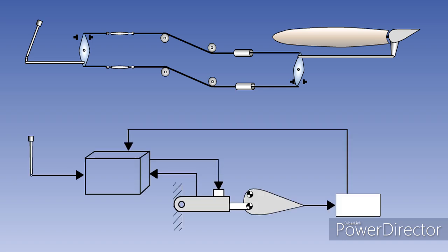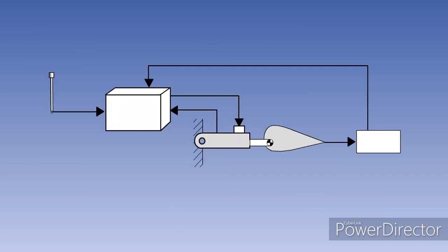Electronically controlled flight controls, in systems known as fly-by-wire systems, overcome many of these problems. By using electrical control circuits combined with computers, designers can save weight, improve reliability, and use the computers to prevent undesirable aerodynamic characteristics. Between the pilot and the final control actuator, a computer system is interposed. This modifies the pilot's inputs in accordance with carefully developed and validated software programs, in order to produce maximum operational effect without compromising safety.